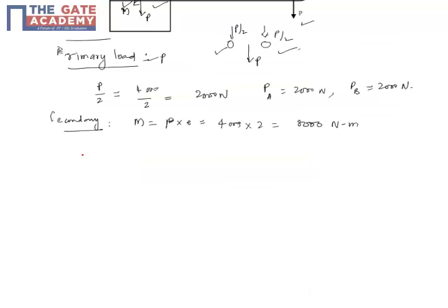So let's see how this produces the secondary load. You have a load here, you have a load here, and this is the centroid. Let's call the distance from the center of the first bolt to the center of the bolts LA, and this is LB. Both are the same here, but just to generalize. And this moment is M. This moment M will produce a secondary load on A, let's call it SA, and on B in this way, because this depends on the direction of the moment.